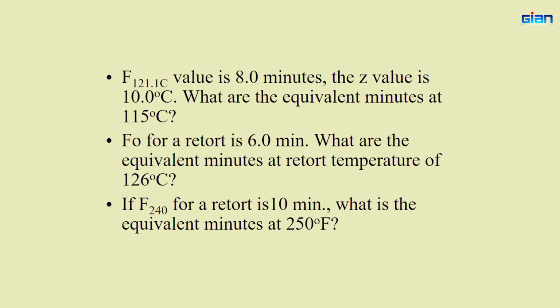You can try to look at the processing time. One thing to remember when you look at these types of problems is that before you get into the math and solve the equations, think physically. In this example, I am processing at 121 for 8 minutes, and the Z value is 10.